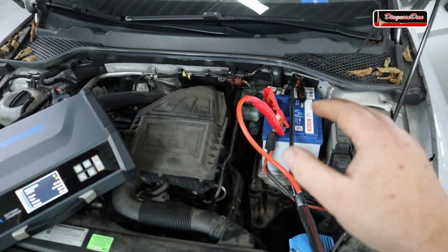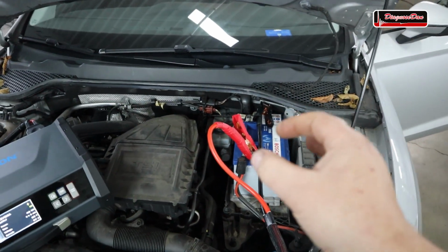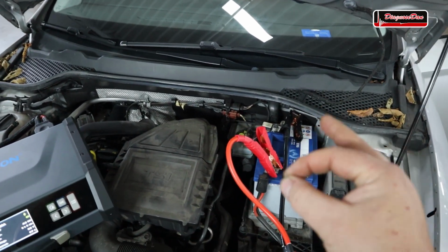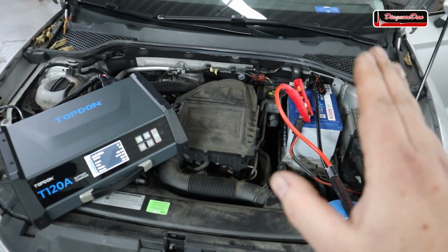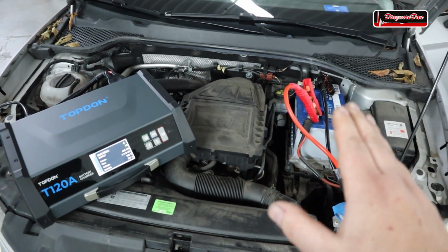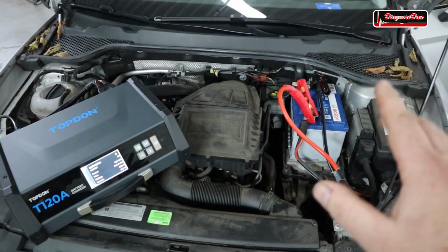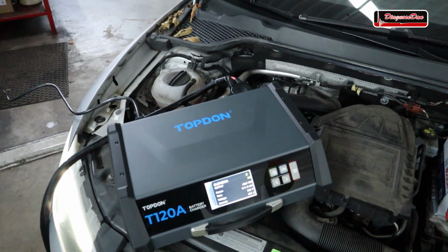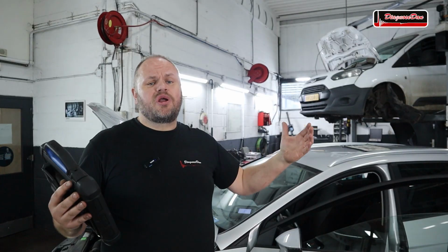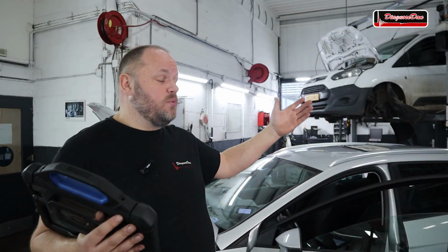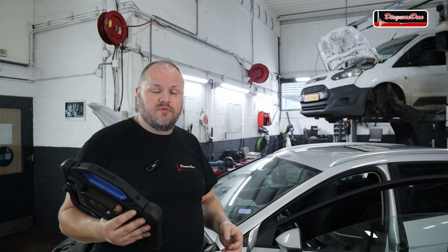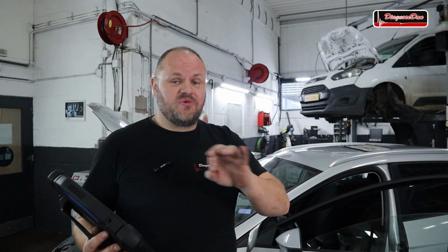Another thing is that we need to take some measurements, and those measurements need to be reliable, where they're not when you have an empty battery. So my advice is, when you're diagnosing a vehicle and you know it's going to take some time, always hook up a battery maintainer. So the customer complaint was easy to confirm. That window doesn't go up or down. Now, we hooked up a battery maintainer, so we don't have to hurry and we don't have to worry.